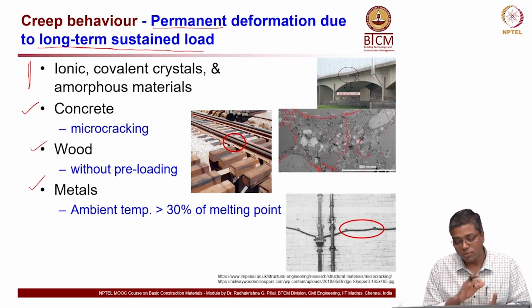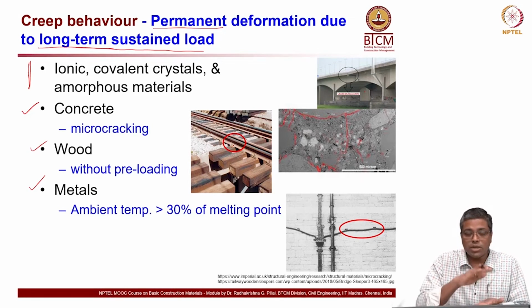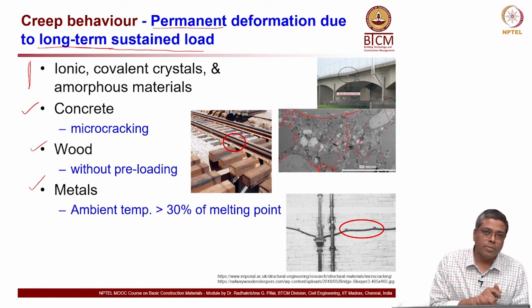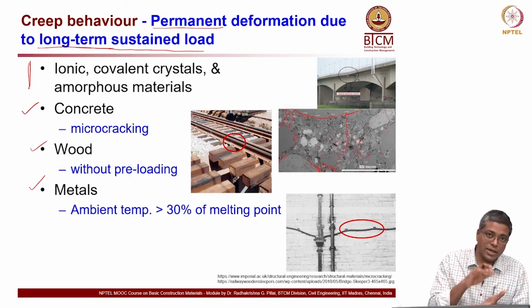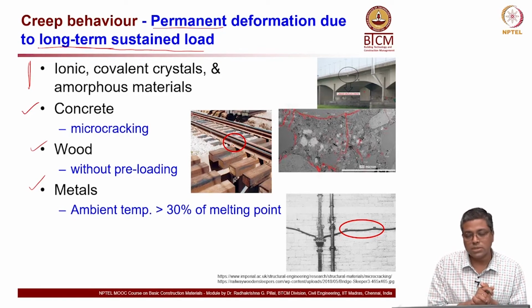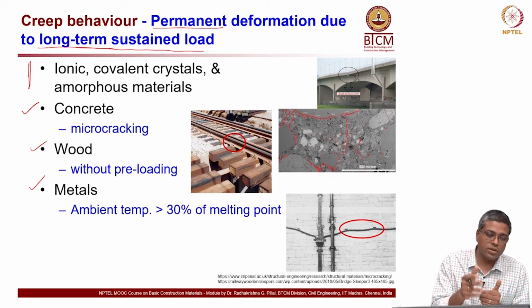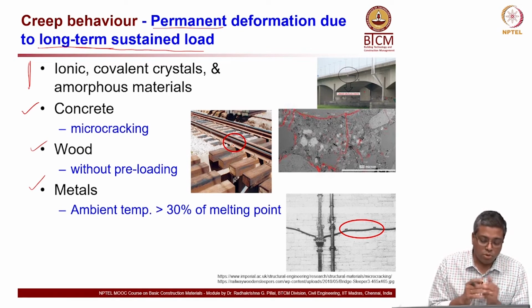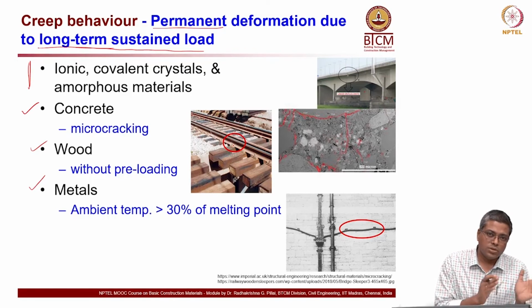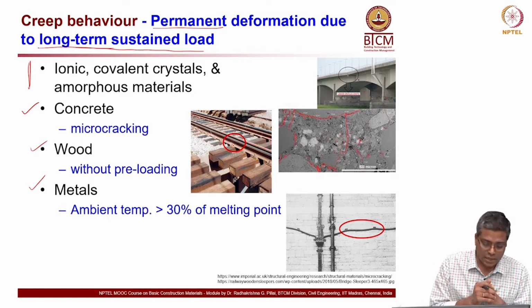rail track. Because of that, the compression which happens after the rail track is placed is going to be minimal. So preloading or pre-stressing of wood is very useful to reduce the creep deformation after the installation. The maximum possible compression you do before the installation, so that after installation it is less.